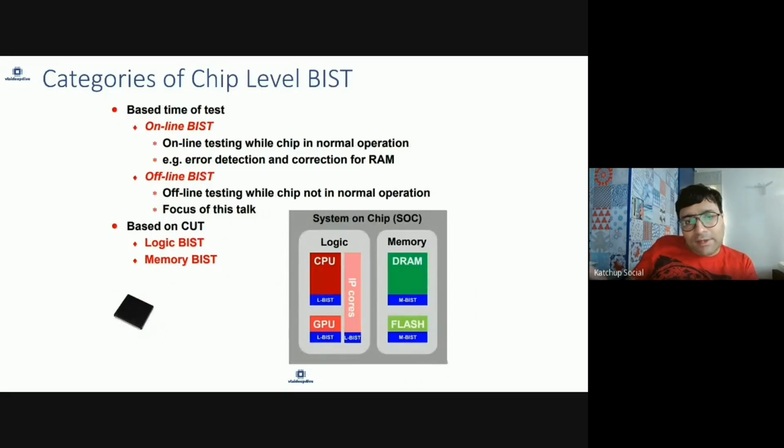There are multiple kinds of BIST. There can be BIST for memory, and there is also built-in self-test for the logic of the design. Typically I've seen it mostly being done for memory, but there is logic BIST also, which is done.